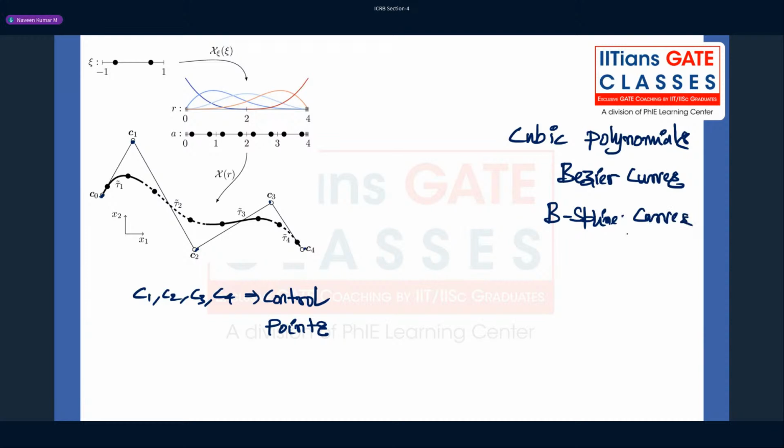The B-spline has been extended to NURBS, non-uniform rational B-splines. There are things called knot vectors, which have non-uniform values, and you rationalize at the end to represent some conic sections. So there is a big area opening there.